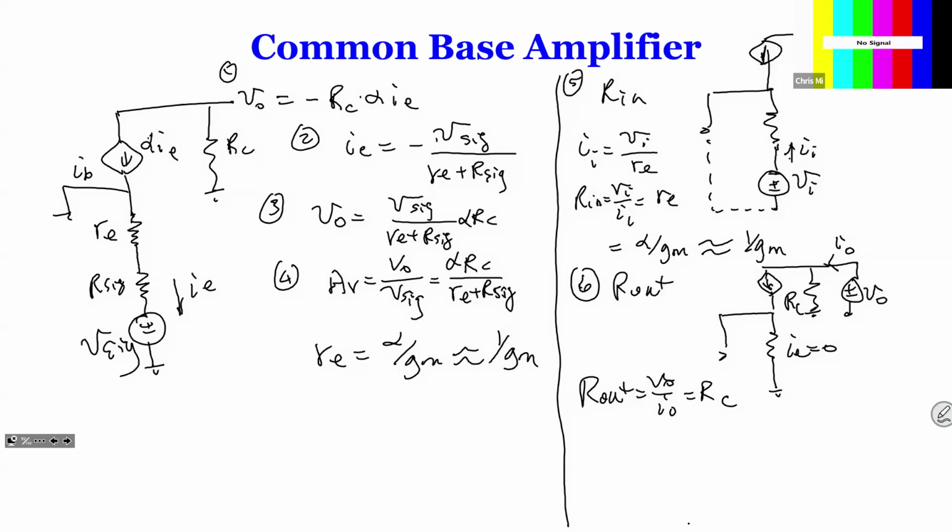I mean, in real life, in the laboratory, let's say you give me a black box device and I want you to find the input resistance. What would you do? Find a voltage source, measure the current, and you'll find it. And on the output side do the same thing, but of course you short the input. So that's it. Yeah.